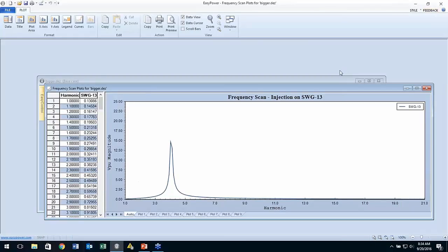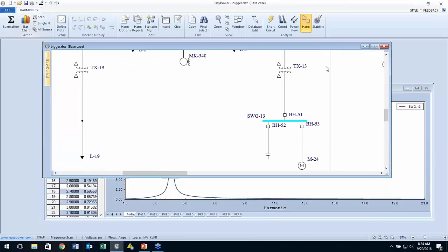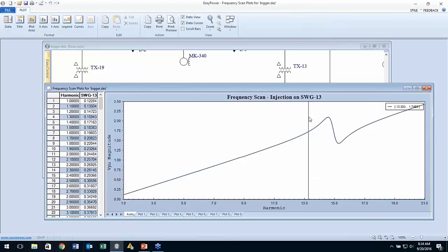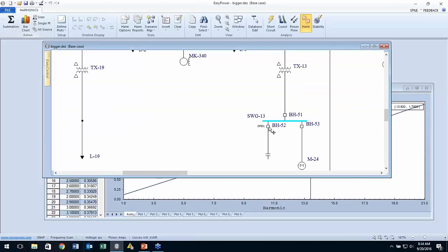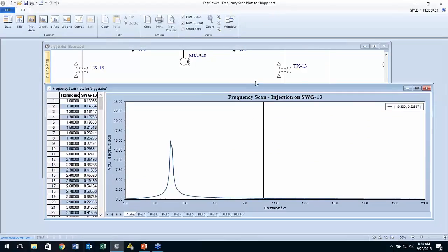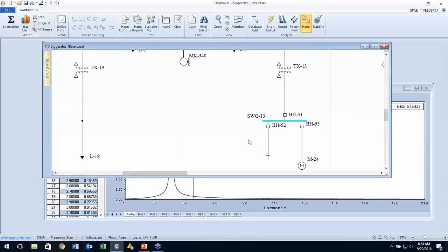And so at that point, I think we are well advised to do some fairly serious consideration about what harmonic mitigation is going to be done. Because if I take that capacitor out of there, that resonance point goes away and we're down to a very low response. But you get the point. The fact that we put a large capacitor in here, we knew there was going to be a resonance, so we tuned it intentionally at a frequency that the system would never see.